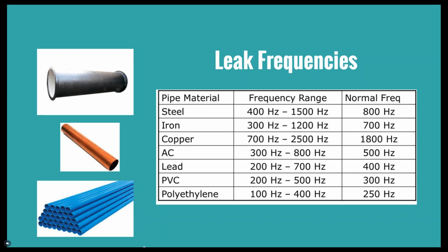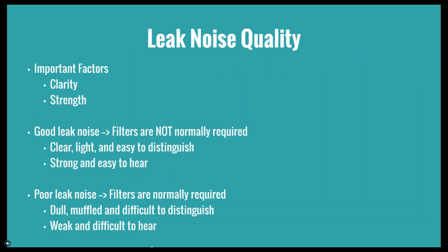So when you are collecting data, verify what your pipe material is with this frequency information that most of these correlators collect when they're collecting leak detection data.